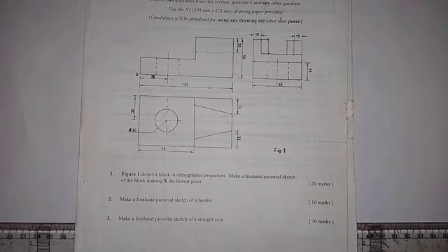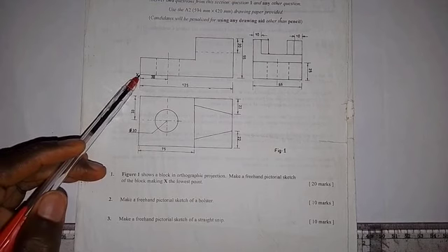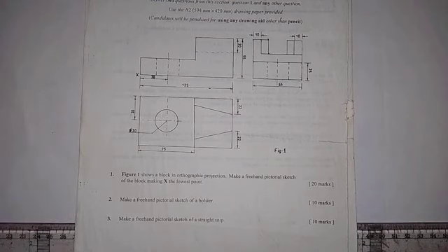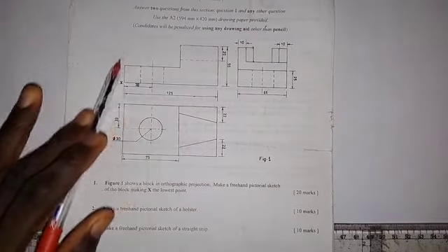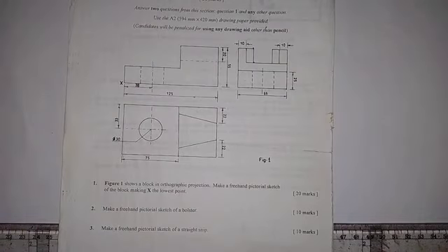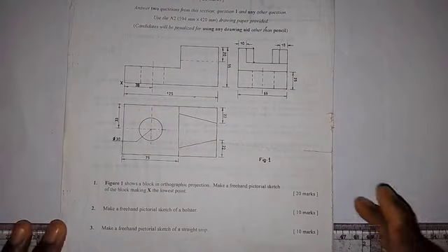So we are going to put all these dimensions, making use of them for us to obtain the isometric view of this object. And very important, we need to take note of the lowest point, and this is the lowest point X that we have here. Okay, these views are given in first angle projection, as you know. So let's go and produce the isometric view of this object. The first thing I'm going to do here is to produce this shape of the front elevation. Then we'll go on and work on the other part. So it's very simple. So let's start.